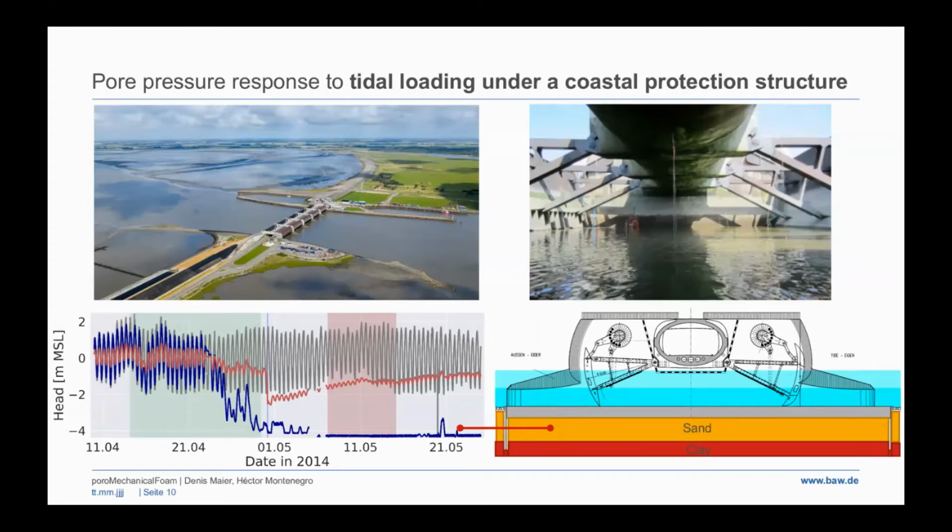And the interesting part here is that we only see pore pressure amplitudes of around 30% of the loading from the outside of the tidal water level fluctuations, which we only really could explain with entrapped gas in the sand layer.